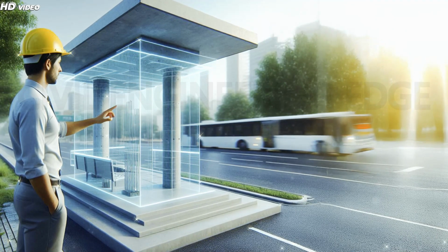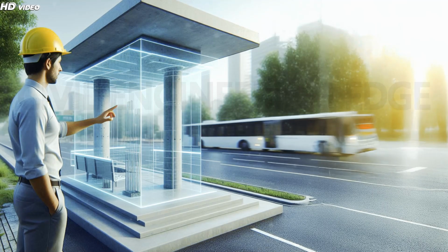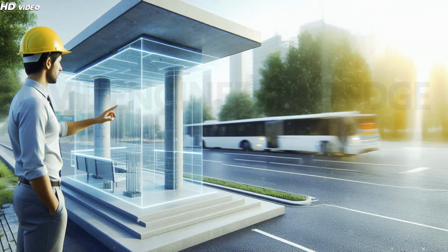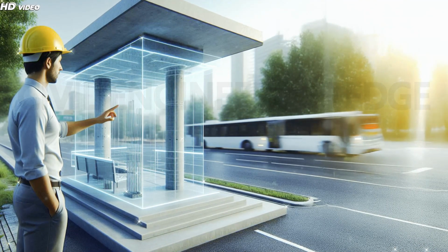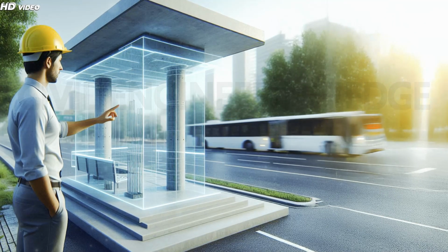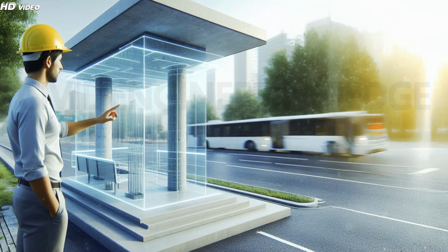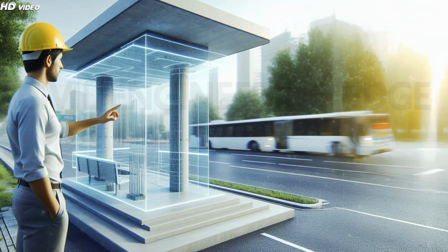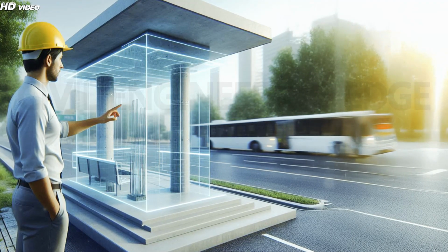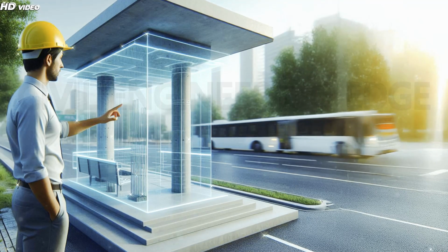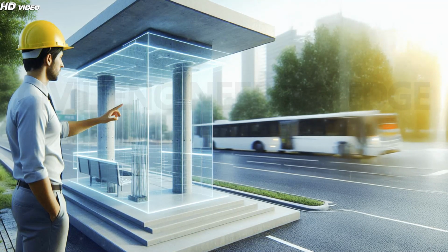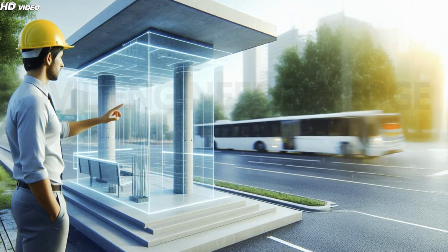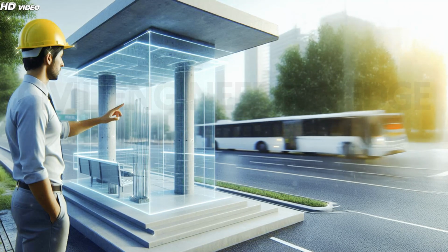Civil engineers now use advanced modeling tools and real-time stress analysis to ensure structural integrity, reduce material waste, and fast-track construction timelines. A bus stop frame usually consists of a continuous slab supported on a number of frames of the type shown here, at a spacing of 2.50 meters to 4.00 meters centers. The supporting frames are usually precast.